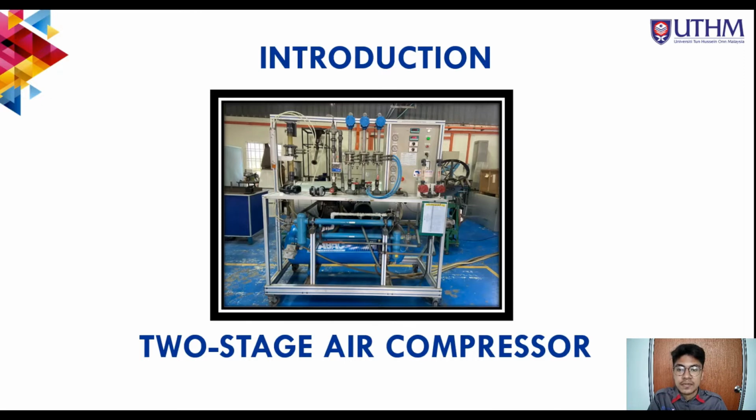A two-stage air compressor usually has two air storage chambers and two pistons for pumping air. At the first stage, air is drawn in and compressed to an intermediate pressure. After being compressed in the first stage, the air is piped through a heat exchanger where the intermediate air is allowed to cool down and then compressed in the second stage. Furthermore, there is an aftercooler in the two-stage compressor that works to reduce the temperature of the air and remove moisture from the air. For this open-ended experiment, we will study the two-stage air compressor and do analysis and further study based on experimental data.